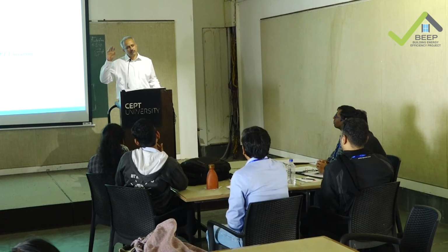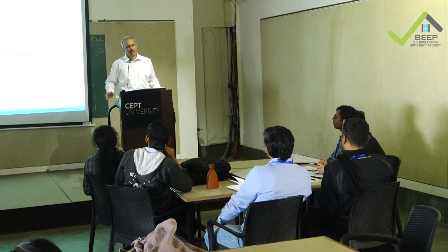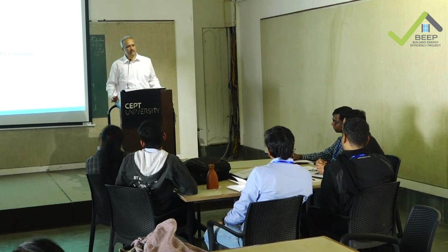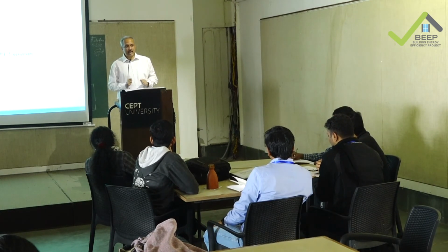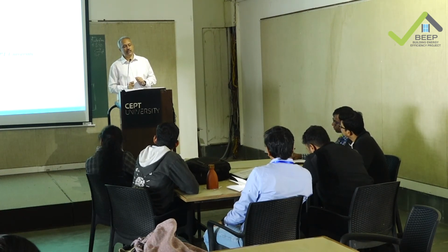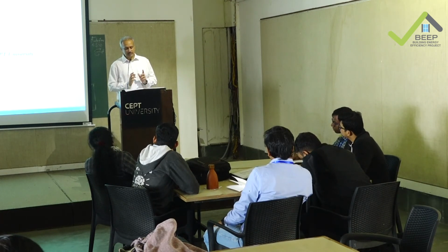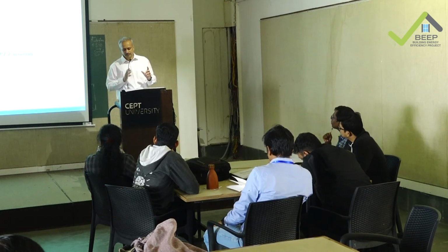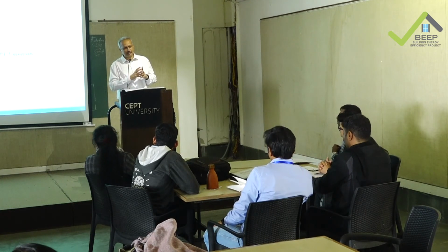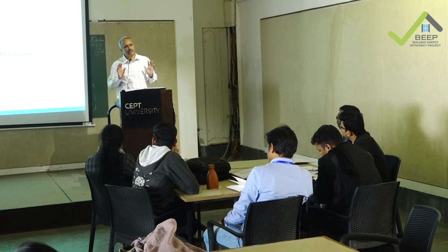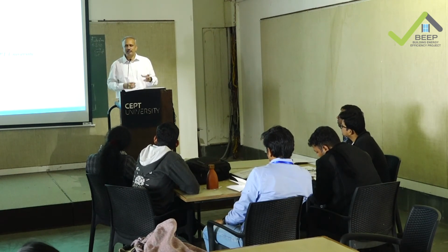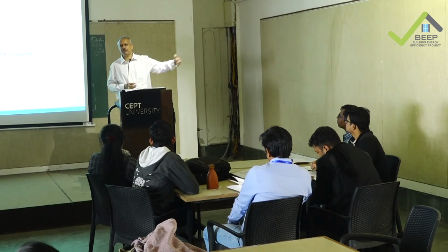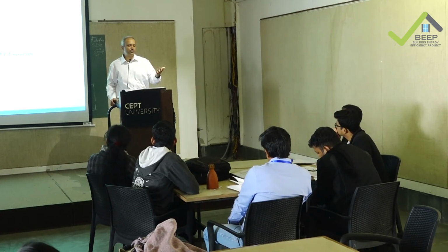If you want to deal with the conduction heat transfer, deal with U value. If you want to deal with the solar radiation, deal with SHGC. If you want to deal with the daylighting, deal with the VLT. Now, when you take up a glass and you want to work with the glass VLT and SHGC, there are some limitations. But if you manage VLT and SHGC together, you can get whatever U value you want to get. But this nexus between VLT and SHGC, if you want to split that, the best option is to go for shading. The moment you go for shading, you are not at the mercy of material science, where VLT and SHGC will be dealt together. Your VLT could be separate and your SHGC can be separate, provided you manage through the shading.